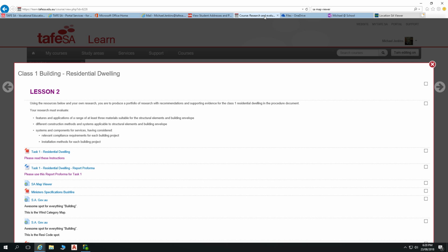Some of these points, so maintenance requirements, is that just basically upkeep, how long it's going to last? Yes, exactly. So typically a lot of your maintenance for your framing is not important, certainly if you've got all your weatherproofing details correct. However, you've probably noticed that on almost any house of a decent age, fascias are your first entry point of rot. Probably exclusively, we should use H3 LOSP treated timber for fascias, so it's suitable for that application.